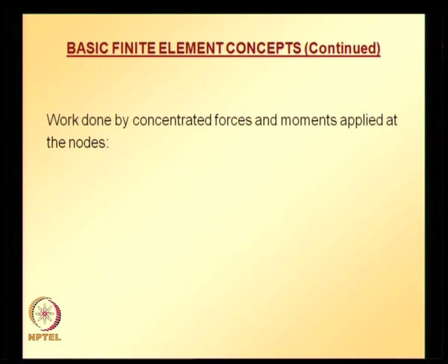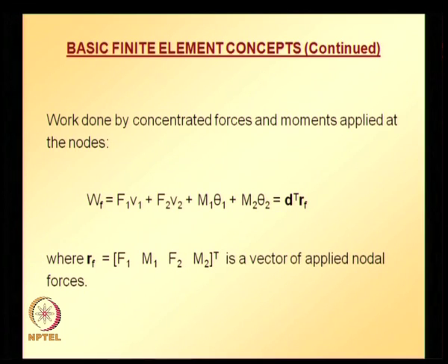Now the work done by the concentrated forces and moments which are applied at the extreme points of the 2 node beam element, which are nothing but nodes, is given by force times displacement and moments times rotation. This can be compactly written as d transpose R_f, where R_f is just a compilation of all the forces and moments, F1, M1, F2, M2, a vector of applied nodal forces.